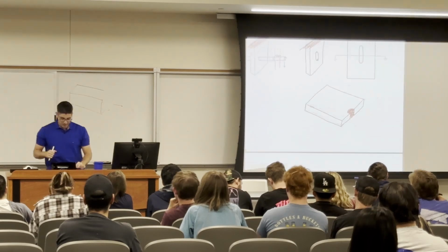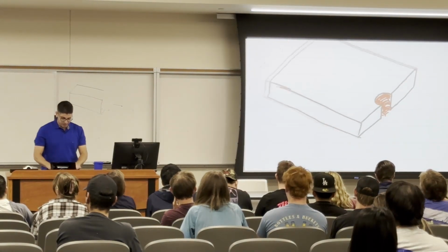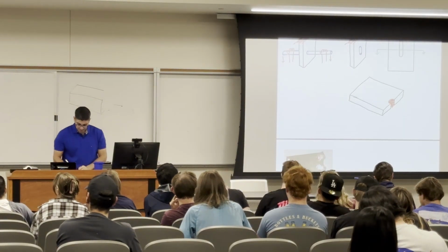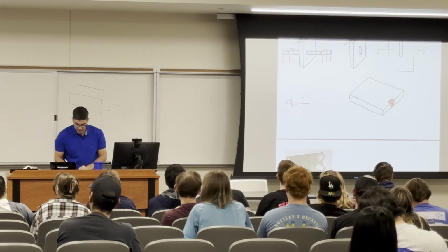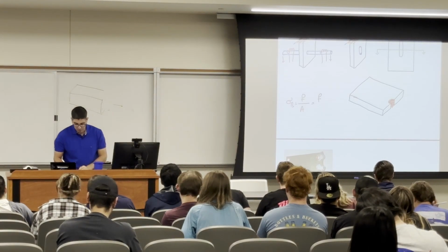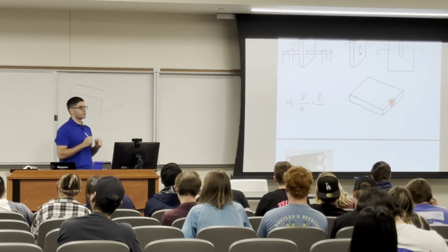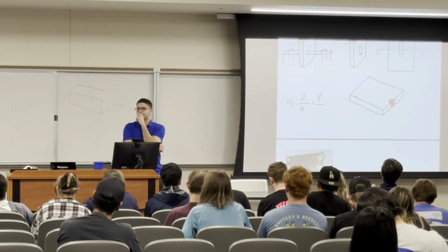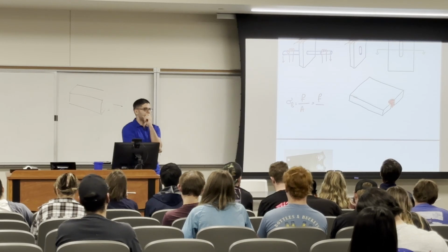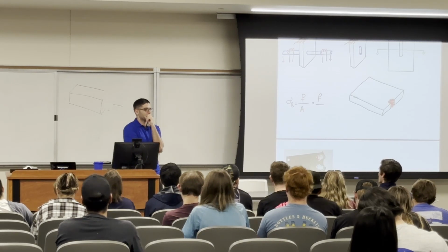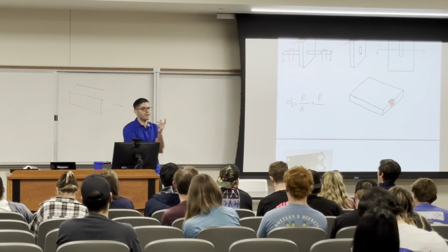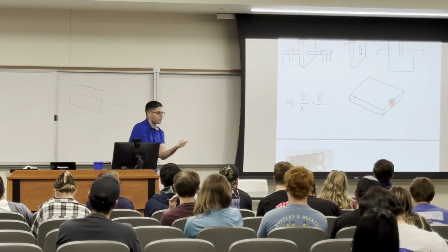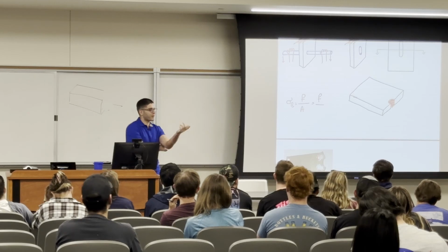So if I have, let me see if I have this. The bearing stress, which is sigma because it's normal, again, is going to be force over area. So, okay, we know the force, which is my weight. What area should I choose? Yeah, you can throw any guess. Okay, half circle area. What does anyone think? It's like half the surface area of the cylinder, just the body. Okay, that's correct. Times the thickness. Correct, times the thickness.